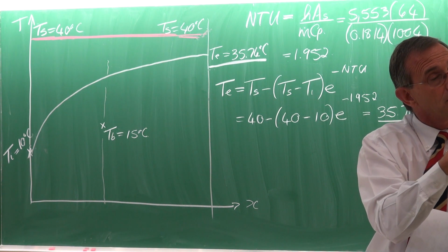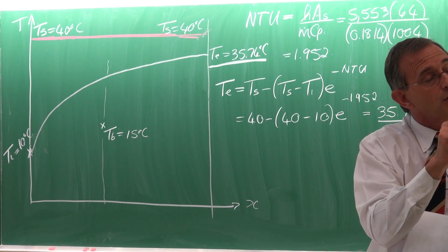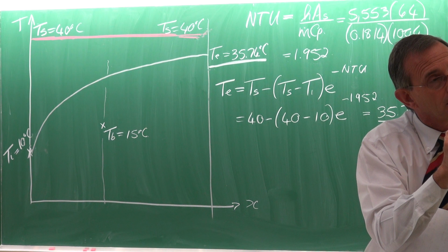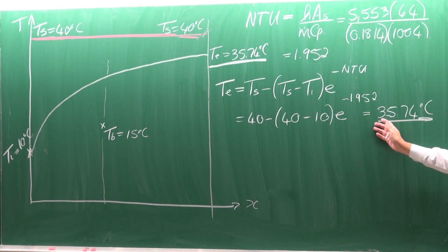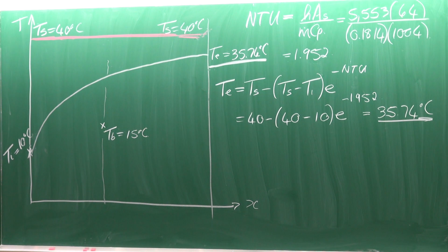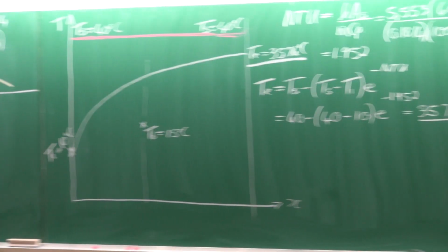But the Nusselt numbers are also based on the Reynolds number, and the Reynolds number is also based on the hydraulic diameter. But if you think of this derivation that we did here, we worked with the area of the control volume. And I think that's the reason. So I think it is correct to use this area and not that of the tube. So let me just go back and revisit this.